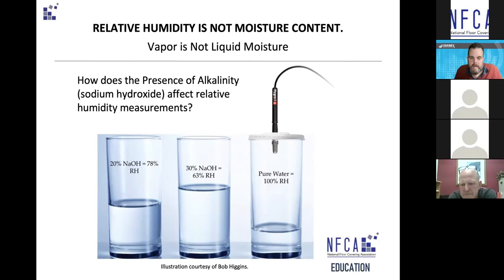The calibration salts check usually uses table salt, I think, which creates an RH of about 75%. So you're expecting the RH to be 75 using the salts, but the salts is water in a container. So the RH should be 100%, but it's not because of the salts.